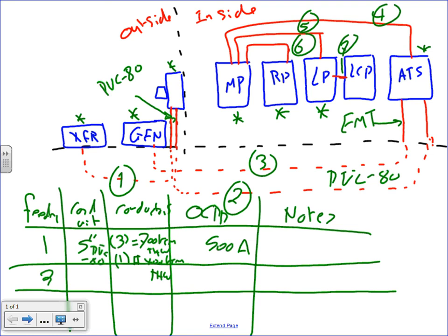We see RMC, but it's steel, it rusted more. It still rusts. You see it outside. That's why we're not using anything outside, or we're using PVC Schedule 80 for physical damage. That's at 15 years. Yeah. Guys, every time you touch Mother Earth with a metallic conduit, it will rust.